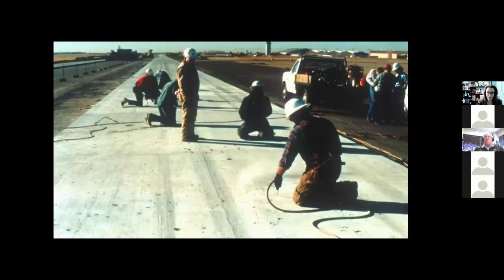So my recommendation for repair of a blister is for where you can't deal with any loss of section of the surface, and an example might be FOD, the foreign object debris, for an airfield. Otherwise, I'm thinking most structures can handle it. It's really about, for this instance, removing all of the blisters. So you can tell this is a government project because they're drilling every single hole and sweeping away the particles and then filling it with a cementitious grout. So that's a personnel thing. They were worried about leaving any debris on the surface, so they did them one by one.